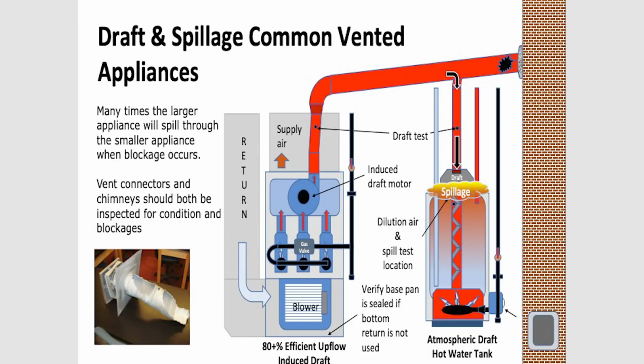This one was absolutely full of aluminum beads, top to bottom. Because what happened was this is a masonry chimney liner. The masonry is cold. They didn't put a sleeve on there to protect it from condensating. The condensate collected on the inside of the liner, and again, it's an acid in there that attacks the aluminum, and then you end up with a rotted out liner sitting there, right? So these are common problems that we see out in the field all the time.